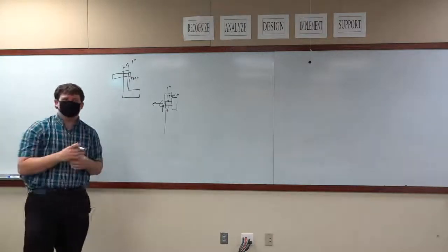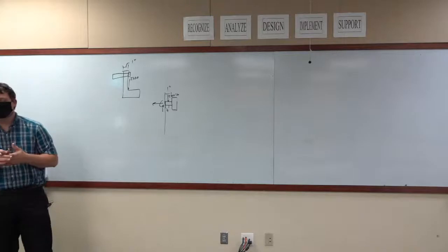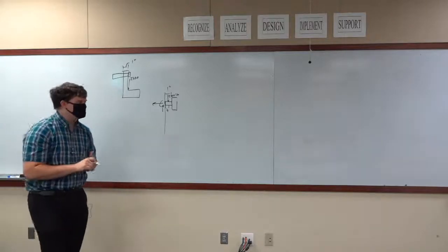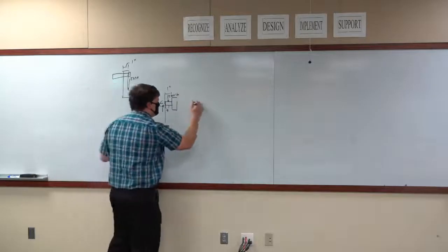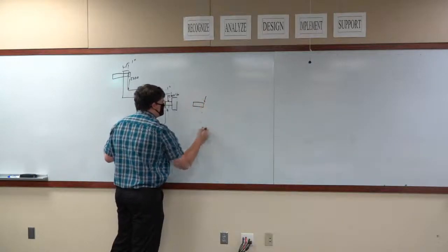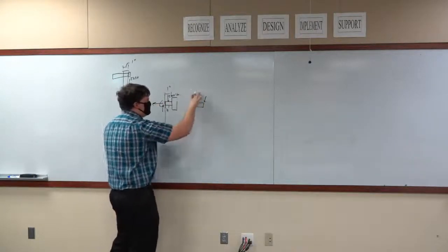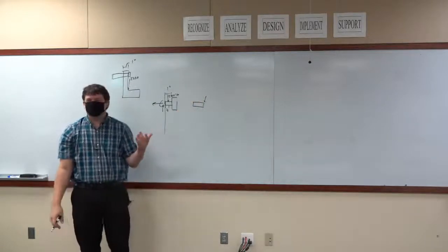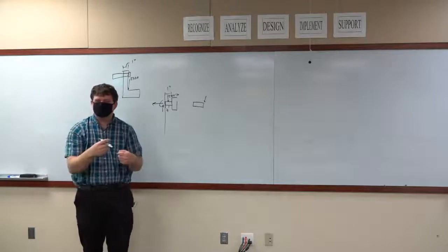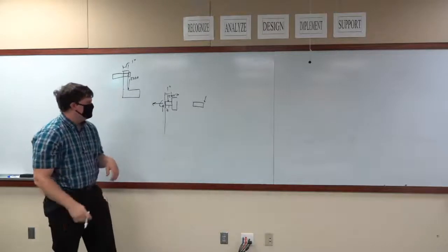Now, I talked with my brother about this and I gave him the problem, and he kind of laughed at me and said, this isn't quite a cantilever. This isn't a system that looks like this, because this can't move. The bracket is rigidly mounted to the wall pretty much with the tension. It comes from the bolt.